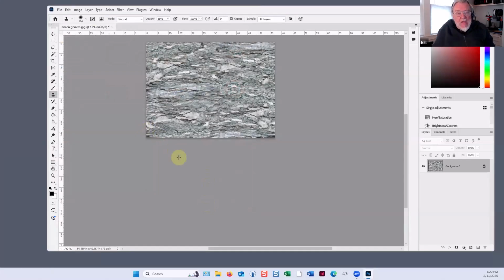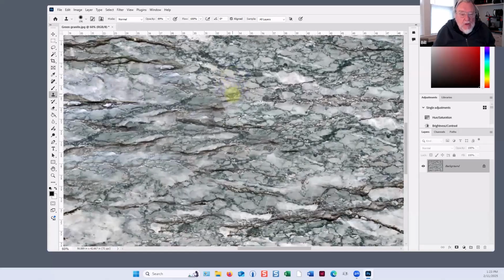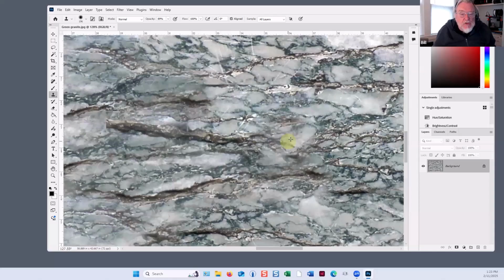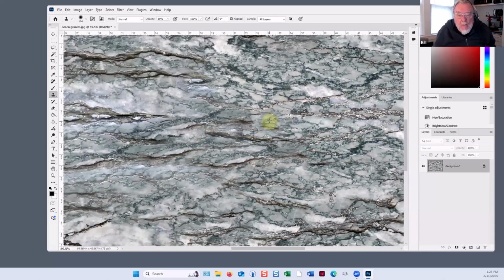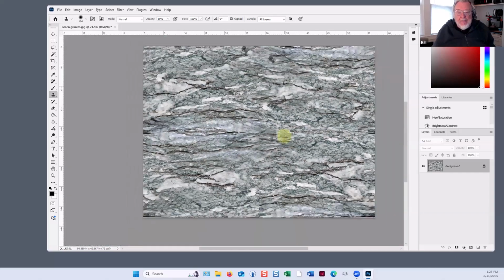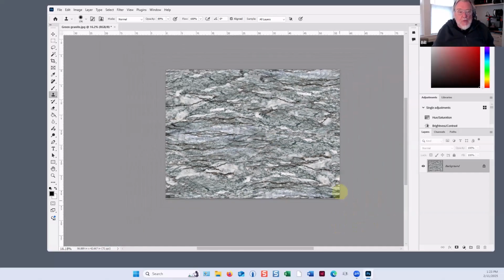Okay. And remember, in Revit, when we create a material using an image, we tell it how big the image is. So I might want to say that this is like 2 feet by 18 inches or something along those lines, just to keep the proportions approximately the same. I don't want to zoom in too hard, or start seeing where our little joints were. Yeah, like there's one right there. But good enough for government work at this point.